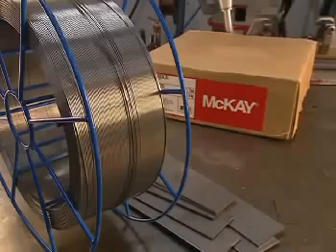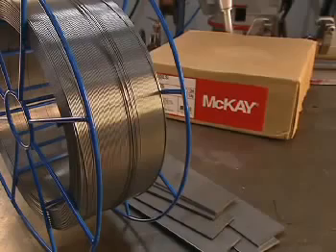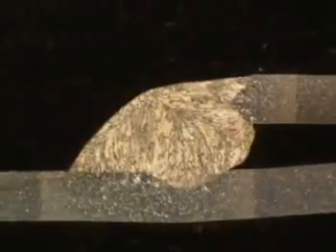To recap, AccuPulse makes shorter arc lengths possible, allowing faster travel speeds and greater control, especially when welding out of position. It allows better puddle control, directed arc, and is more tolerant of contact tip to work variation. It adapts extremely fast over tack welds. Larger wire diameters can be used, which saves money. There's no arc wandering in tight corners and a stiffer arc plasma column. It's more tolerant with poor fit-up and gaps and provides perfect performance with through arc seam tracking.